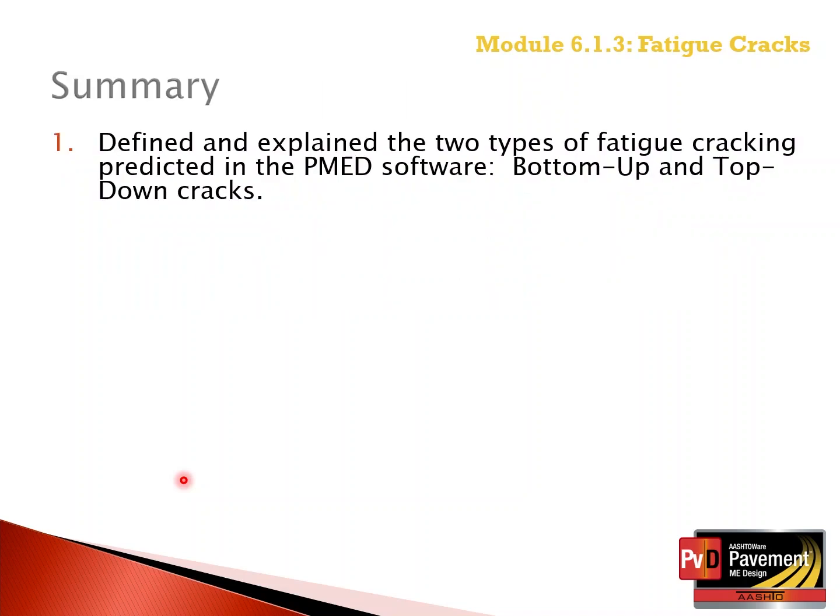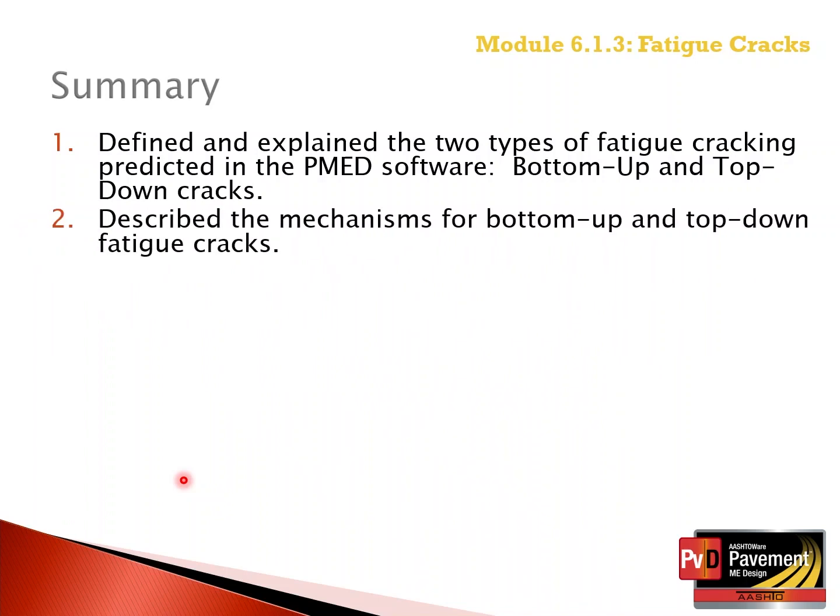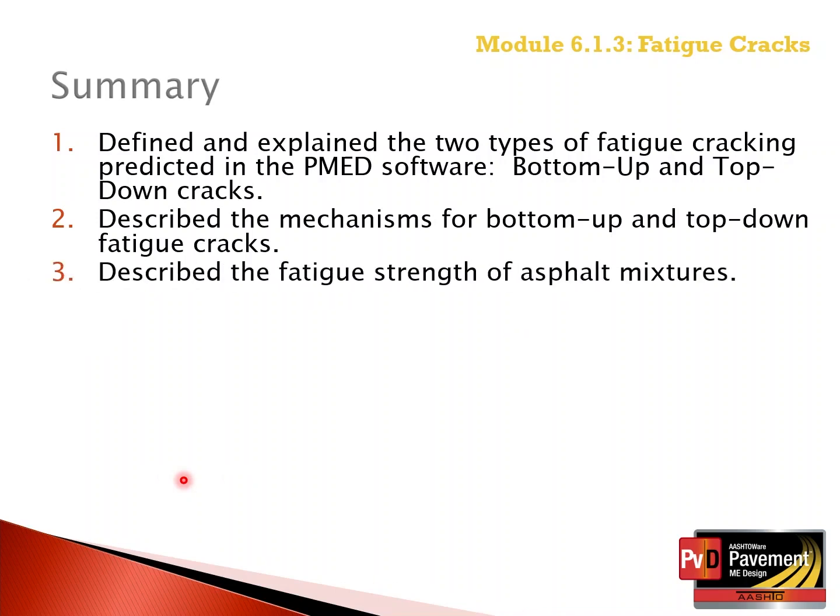So in summary, we defined and explained the two types of fatigue cracking predicted by the PMED design software, bottom-up and top-down fatigue cracks. We discussed the mechanisms for both bottom-up and top-down fatigue cracking. We described the fatigue strength of asphalt mixtures.